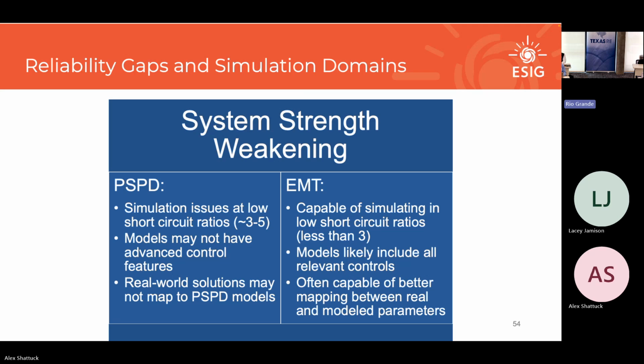And they say, well, the model didn't match the process. And I said, look at the model quality test for ERCOT and it's perfect. And it's like, well, that was the perfect model. It didn't work in the system strength that you're doing it in. You ran the studies on ERCOT's model quality test, which is an infinite grid. You never actually ran something at a low short circuit strength, so we can't be sure how it's going to